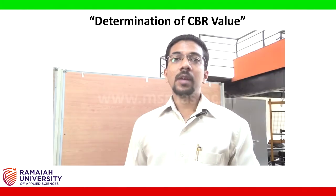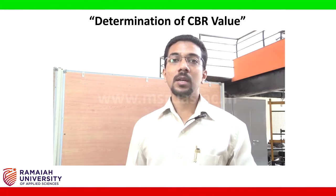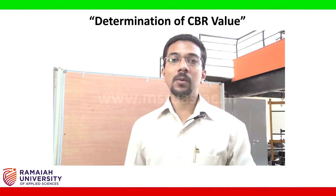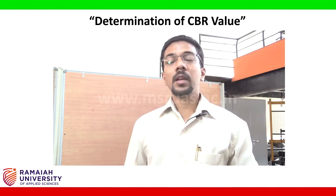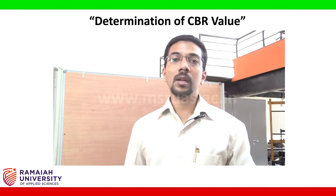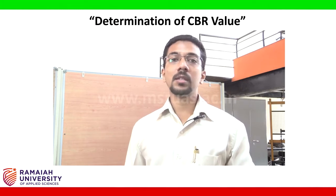Hello students, today we shall be studying about the CBR test. The aim behind conducting this test would be to find out the strength of the soil in terms of CBR value. This test, being an empirical method, doesn't give the true strength of the soil but gives us a comparative strength with respect to the standard specimen.